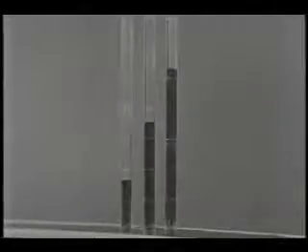Downstream of the bend, the pressure is almost uniform again. The slight variation there is due to a complicated secondary flow induced by the bend. As we increase the flow, all the pressure differences also increase, according to the square of the velocity. But the pressure difference due to curvature remains a constant fraction of the dynamic pressure.